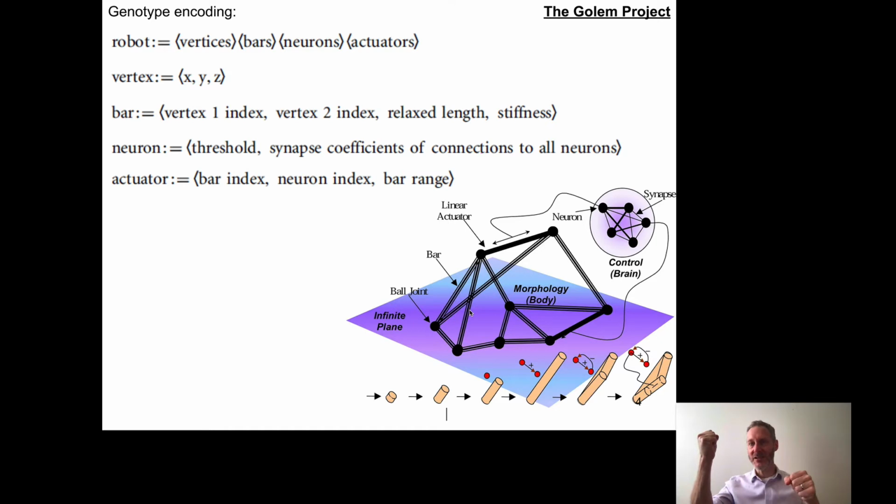The stiffness, as you'll remember, is a floating point value, where a low value represents a slinky, something that's very loose and doesn't take a lot of force to increase its length or decrease its length. The relaxed length is the resting length of the spring. So left to its own devices, if there's no forces acting on the spring, how short or how long does that spring want to be?